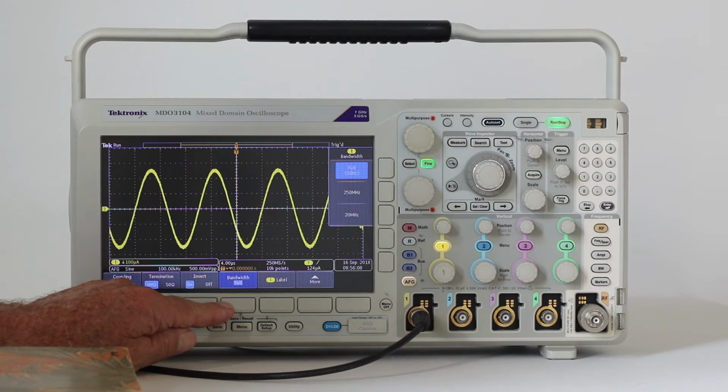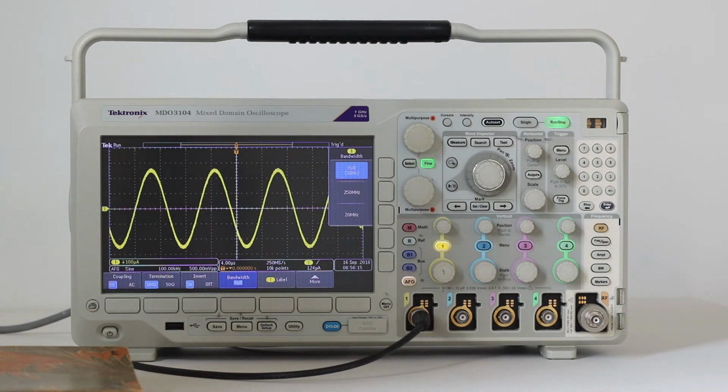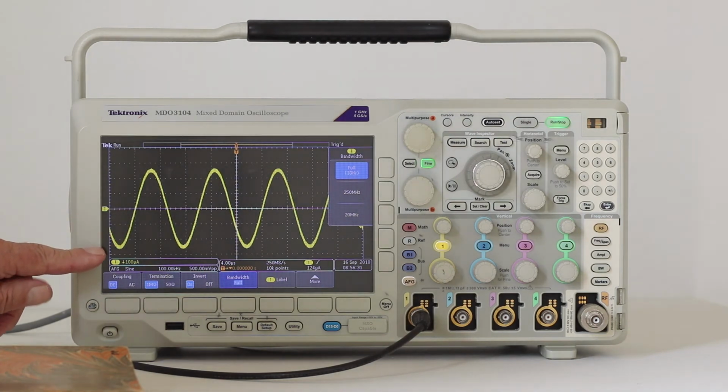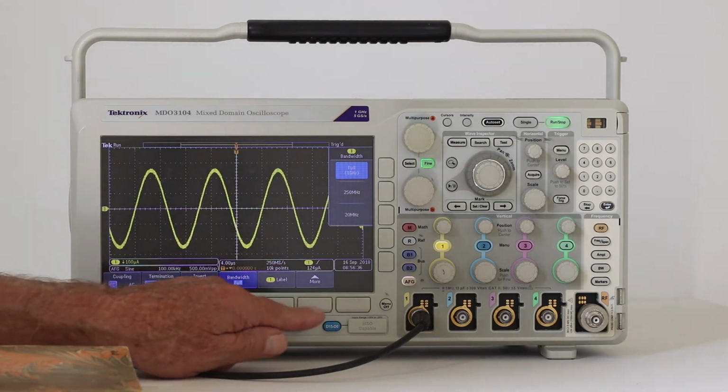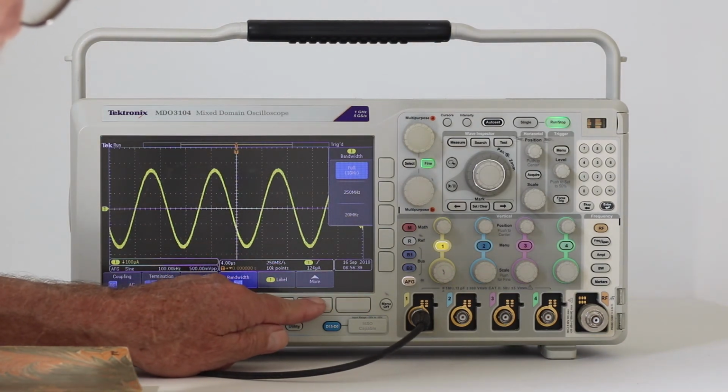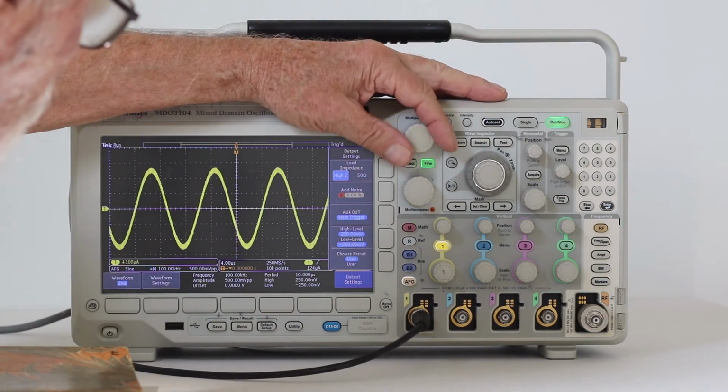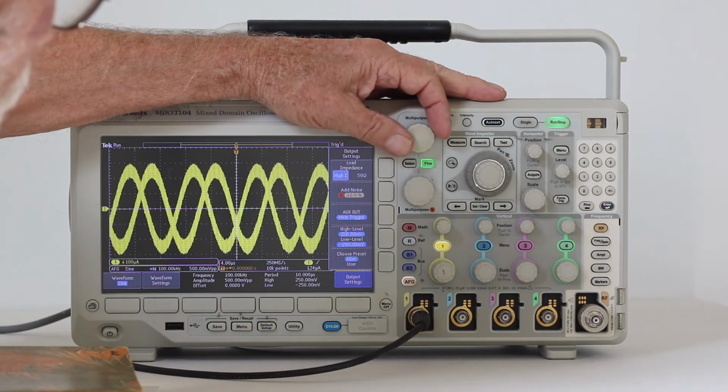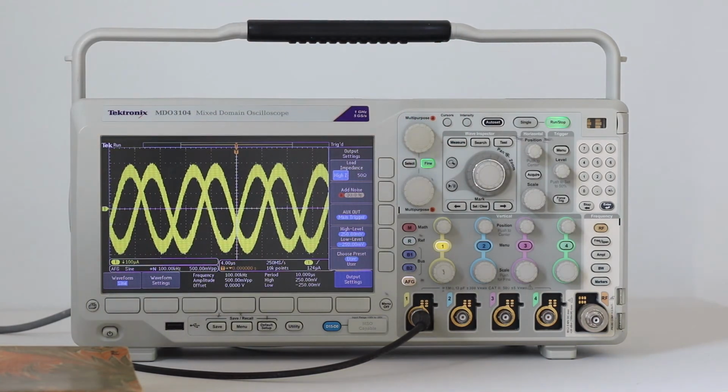Bandwidth permits the user to reduce the bandwidth from 1 gigahertz to either 250 megahertz or 20 megahertz. The purpose is to eliminate noise from the signal, to clean it up. To demonstrate, we'll turn AFG on so that the sine wave in channel 1 is displayed. Then, press output settings and add 30% noise. Notice how the same sine wave signal is obscured, even to the point where triggering is lost.